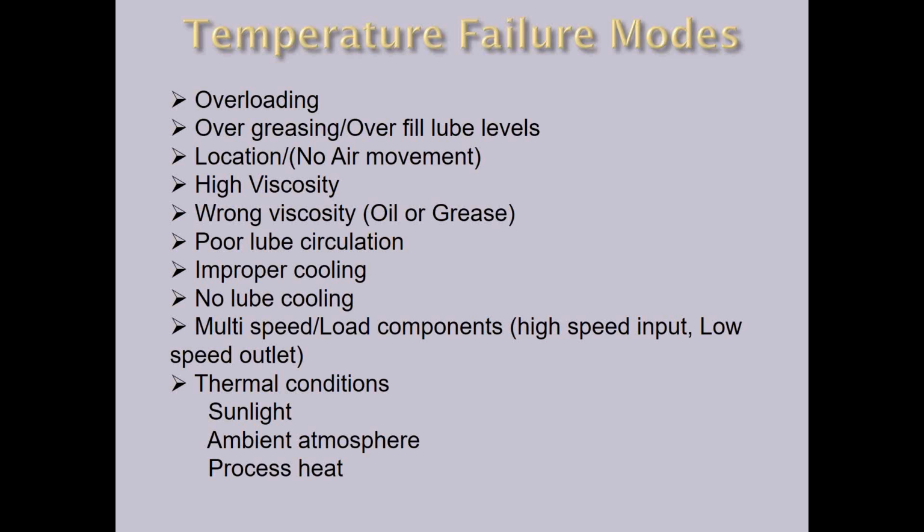Sometimes the location of our equipment, when our equipment's located in an area where there's no air movement around it, setting in a back corner, setting inside a building with lack of air movement, this can cause higher temperatures in our lubricant. If we have the wrong viscosity, if we have high viscosity, it can cause increase in temperature. Poor lubrication circulation.